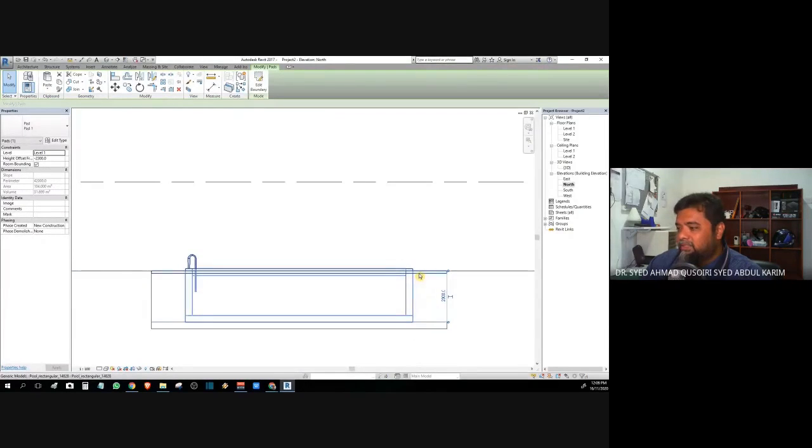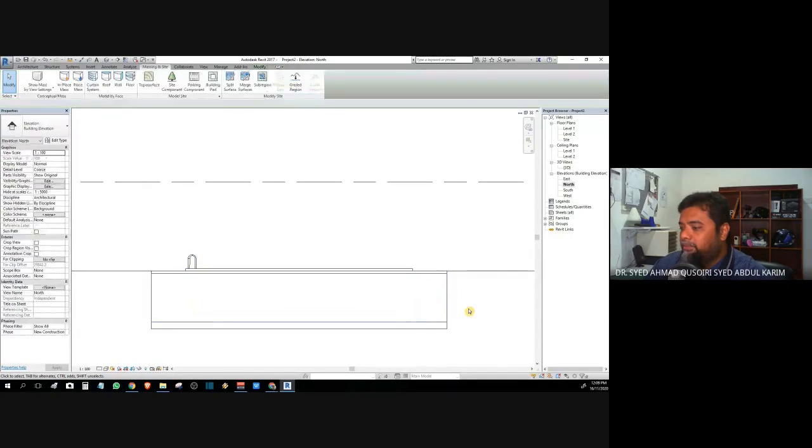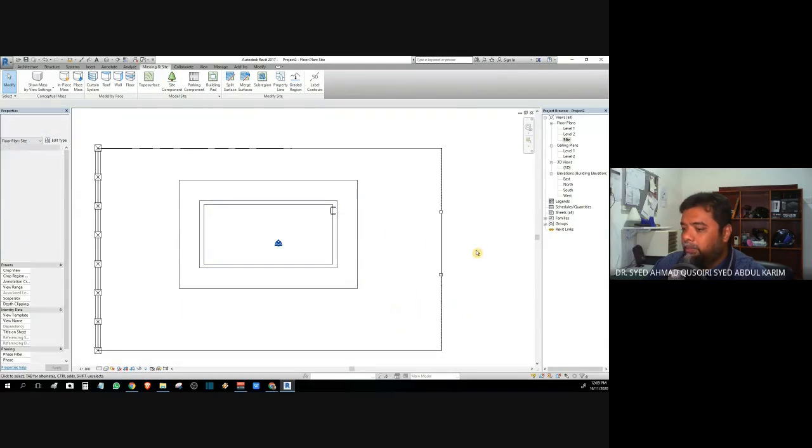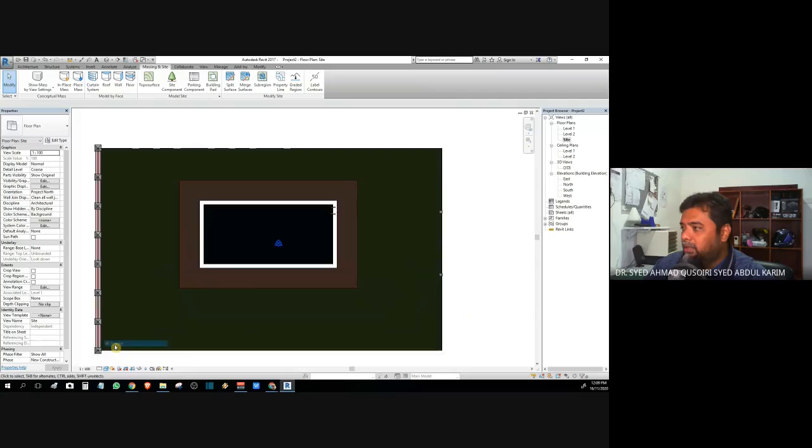I could have just taken the inside here for the pad, but I want to be safe. I don't want to have grass along the perimeter of my pool. So I just take them all. Once I have put the pad over here, of course, you can see the building pad. Shade it. Okay, you don't have any more grass in your pool.